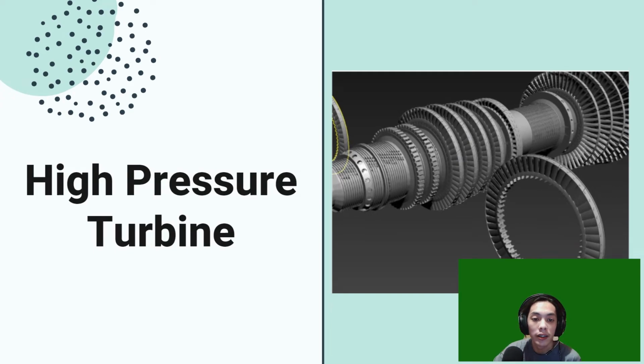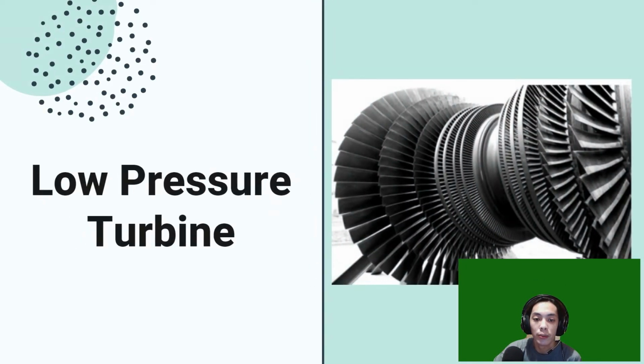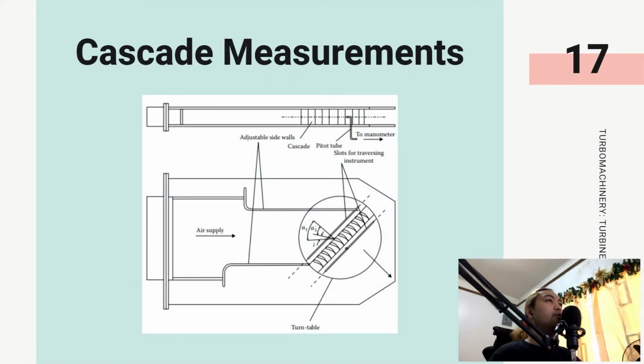High-pressure turbine. In a turbine driving an external load, part of the expansion frequently takes place in a high-pressure turbine that drives only the compressor, while the remaining expansion takes place in a separate, free turbine connected to the load. High-performance aircraft engines usually employ multiple spools. Low-pressure turbine. It is uniquely designed to provide high aerodynamic efficiency in low-pressure ratio operation to recover exhaust energy whilst minimizing back pressure.